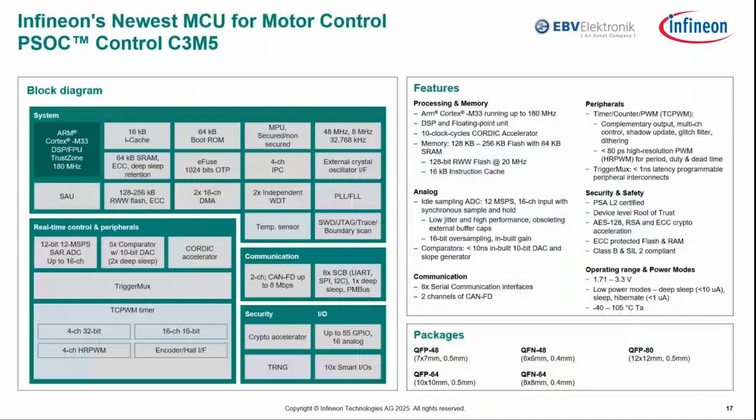And if we take a look at the block diagram of this product, we can see that it's a microcontroller based on the Cortex M33. In addition, it features DSP and FPU units, DSP being digital signal processing and FPU floating point unit, sorry, which enhance performance for motor control applications. And of course, Cortex is a must-have, and it's included as well.